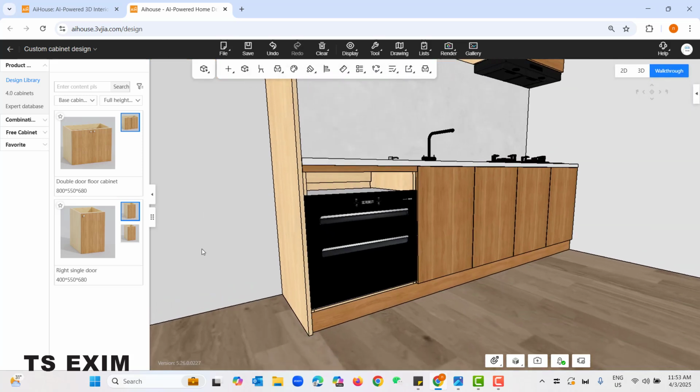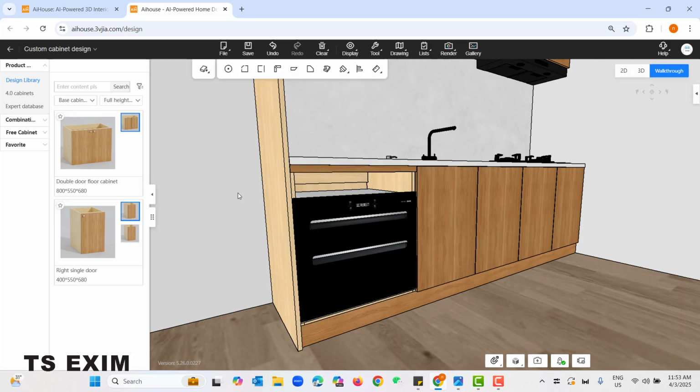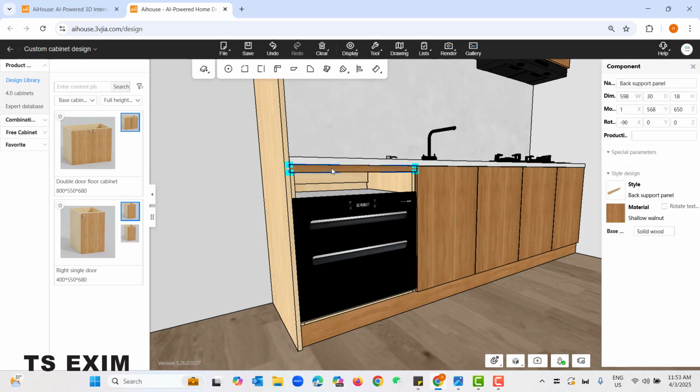Then to select the filler, you need to press B button. Okay, so you press B, select the filler and adjust the sizing here. Okay, so I will extend the depth 130. Okay, we plus another 100. Then to move it down, you need to adjust inside here, Z angle. Remember, to move down, you must put negative value. So you minus 100. Then it will move downward. Okay?